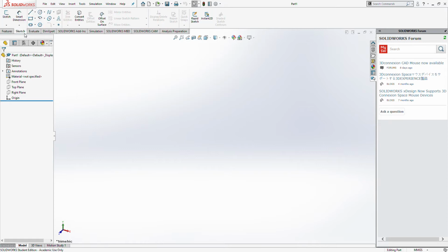Then you have your Sketch tab, which is where you create the 2D outlines or shapes that eventually get modeled out and extruded. With Sketch, you simply draw an outline of something. We'll visit that later. And then with Smart Dimension, that's how you breathe measurements and life into a document by giving it the exact amount of precision that you want a line to be lengthwise or a certain angle. All that's done with Smart Dimension, perhaps the most important tool in SolidWorks.